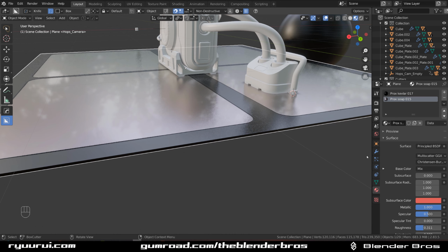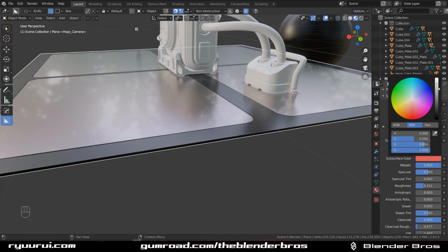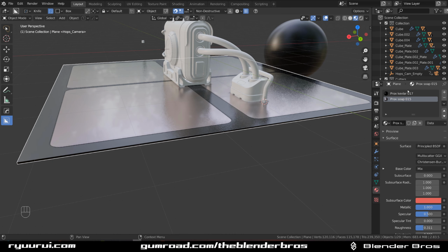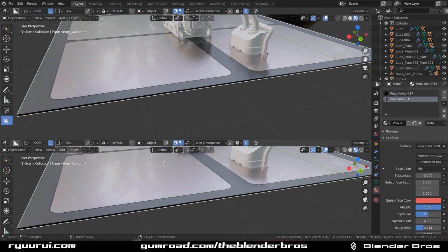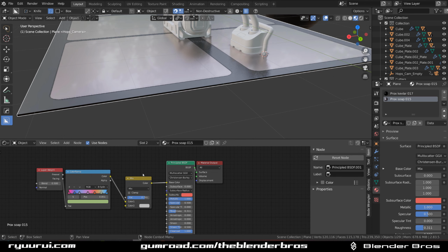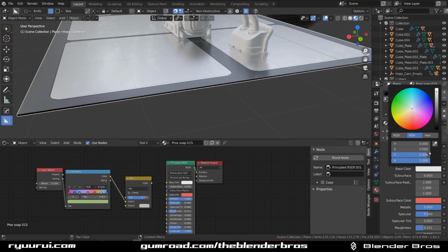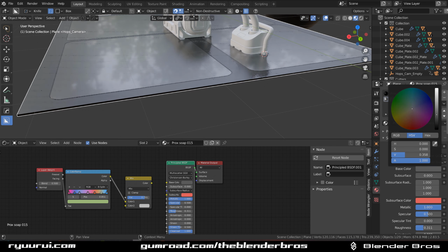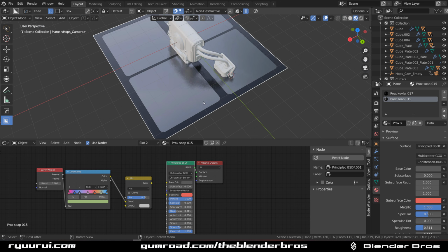There you go. And we're gonna definitely drop some color on it. So where is it? It's not this one. Wait a minute. Base color mix. What? Hang on a second. Shader editor. Let's see what's going on. Color ramp mix. Interesting. Let's just turn it off for a second. So hold Control and right click and cut it out, so we can actually change the color of this thing ourselves like this. I can't be bothered to fiddle with these.